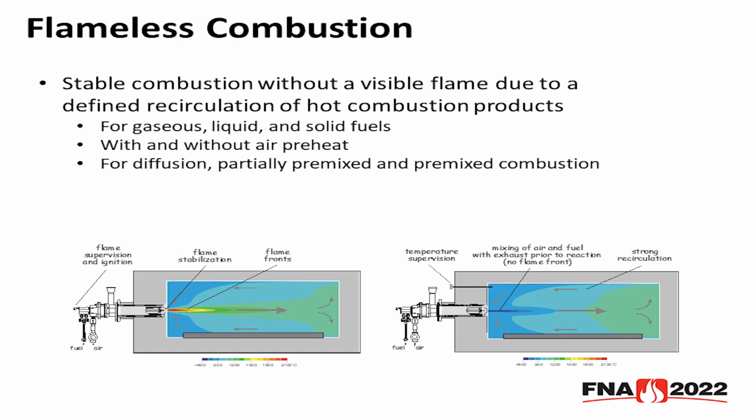So it's a special combustion technology which occurs above auto ignition temperature, which is generally around 1400 degrees for natural gas. But with this technology, you need an added layer of safety. So you typically switch into flameless combustion at around 1550 Fahrenheit.